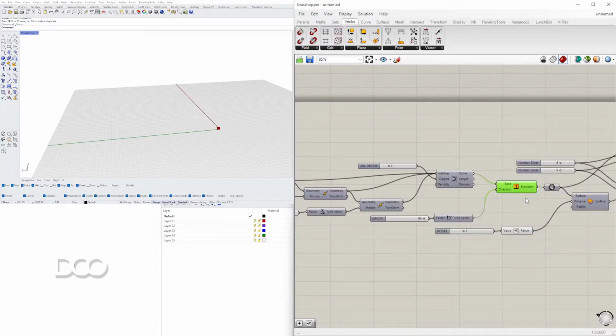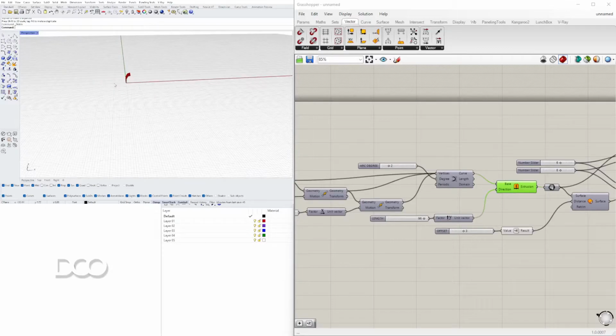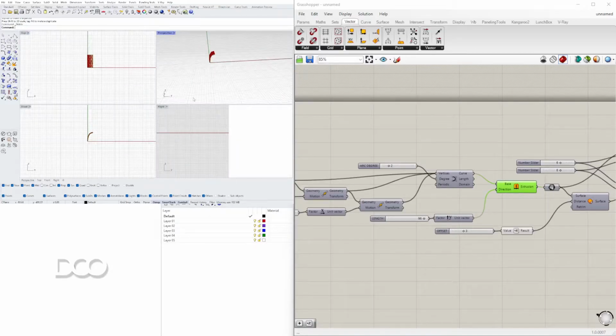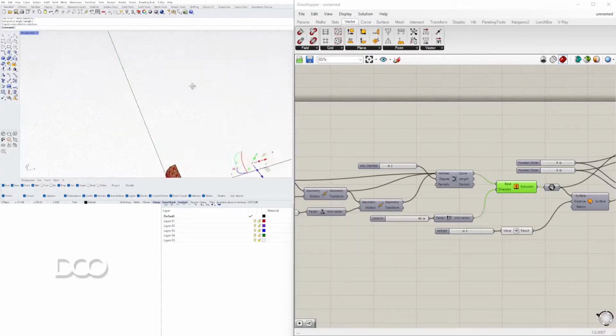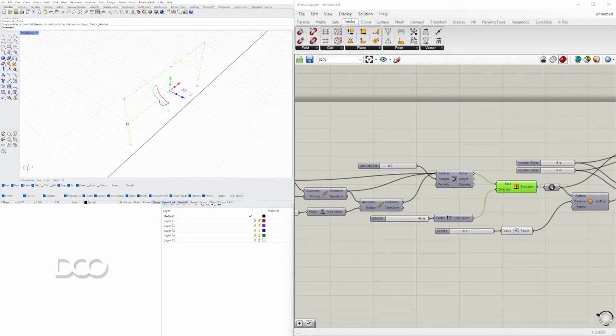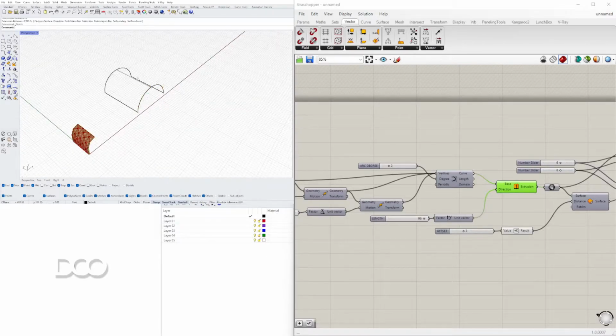I was trying to create that base surface, but the surface is small, so when I created that other one that was so large, it did not work. So let's create it again. I'll go here and create an arc, starting anywhere here. I'll take this arc and we'll extrude curve by whatever amount this way.